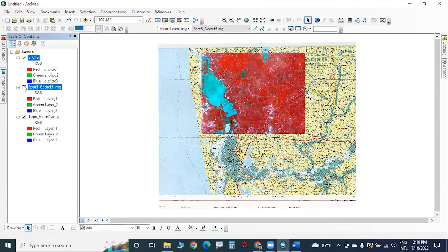Click on and off and see is it clipped or not. Clipped. The exact area is clipped within the image limit. It is clipped. That means what? If the clipping exercise is done incorrectly, what does that indicate in this clipping job? No one gives an answer. I know it. So that means the topo sheet is now in national coordinate system or local data.